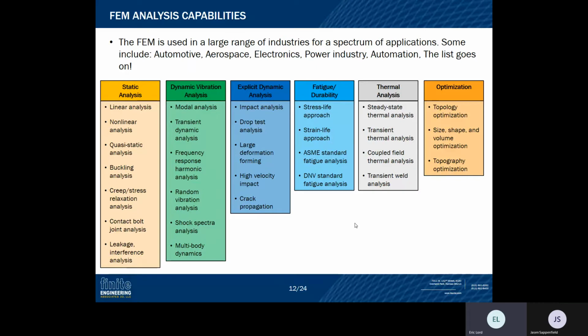So you can easily say very early on in your design process, if you're using finite elements, that, okay, this area has a concern. It's only going to last for X number of cycles, but I really want that to last for X plus 100% cycles, let's say. So you can interrogate certain areas and say, okay, let's go back and redesign just that one area or just that one component. So this is really where the value comes into using finite elements.